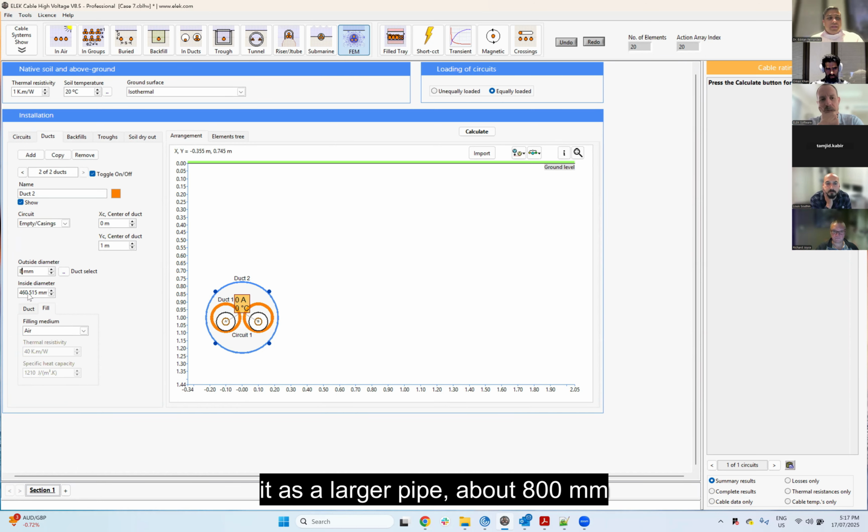Someone asked a question in the chat. I believe it is why do we do it? This is because TB880 assumes that the diameters or the thermal resistance may not be accurate. So just for a safety side, we reduce the current rating to the nearest value depending on the value of the current. Can we see the mesh plot, and then we'll go to some questions, I think.